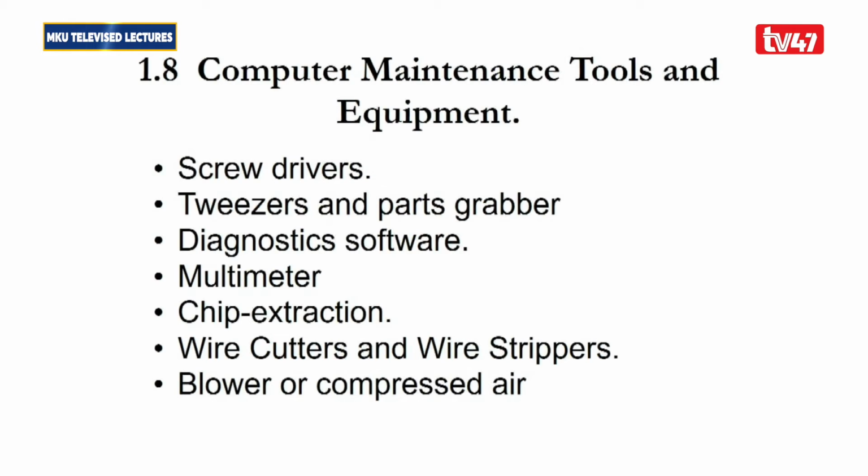We also have the multimeter. This one is for testing voltage, the amount of voltage that is getting into the computer or getting to the different connectors and different parts within the system unit. So it is used to test connectivity through power, which is very important because you are able to measure the exact voltage and know why a particular component is either not working properly or is experiencing some problems.